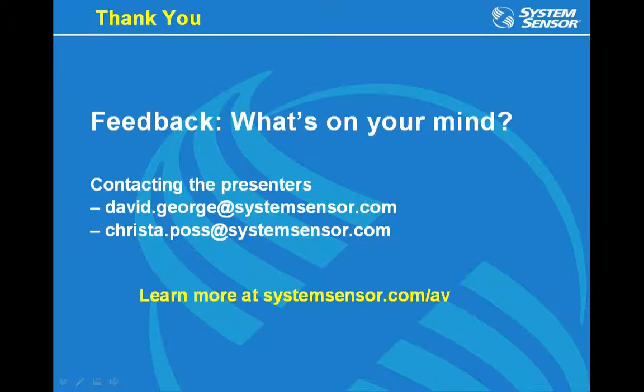This question is somewhat related to that. If they put a circuit together and they wanted to add a device in the middle or at the front or at the end, what flexibility do they have? Is that a drag and drop feature, or how would they complete that in the volt drop calculator? That piece of it is drag and drop within the circuit layout. So once you have your circuit and you've added your devices, you can then move them around depending on where you want them within the circuit. So that is a drag and drop functionality.